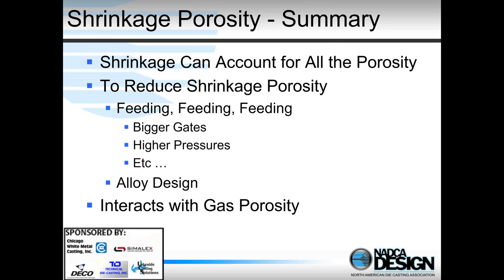And the way we do that with die casting is after the cavity is filled, the plunger applies very high pressure to the biscuit, generally greater than 5,000 psi, maybe as high as 10 or 15,000 psi. Because what we want to do is push more liquid through the gate to supply more liquid to compensate for this volumetric contraction that's going on as the casting is solidifying, and we call this feeding the solidification shrinkage.